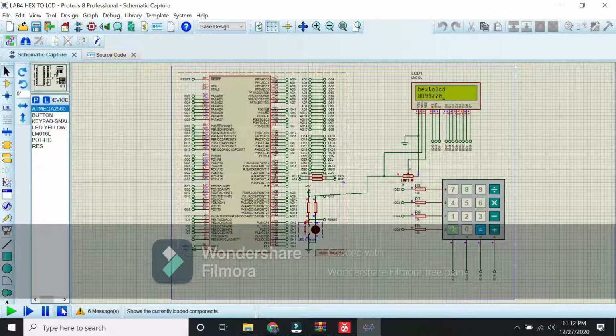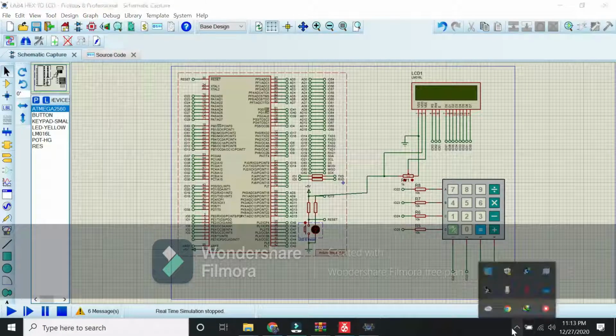In the physical LCD, we have many ports, A and K for anode and cathode for the backlight of the LCD. But here we don't have those ports because we don't need any backlight in the simulation. So here we are done with the first 4 labs now.